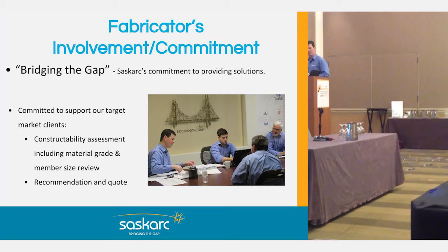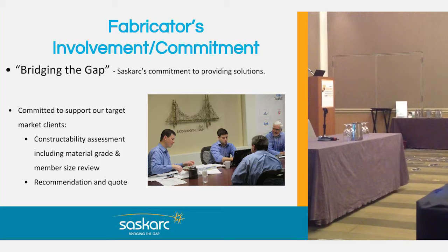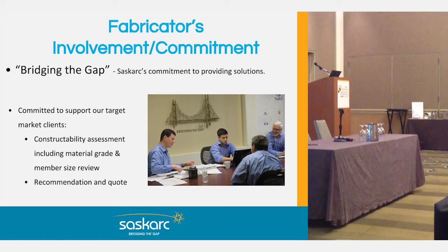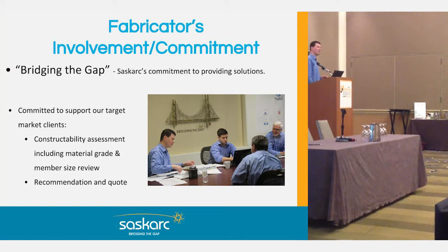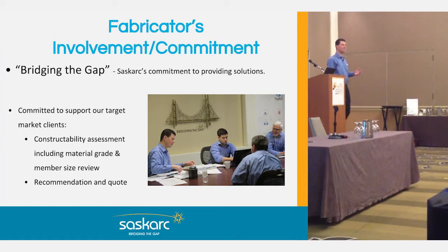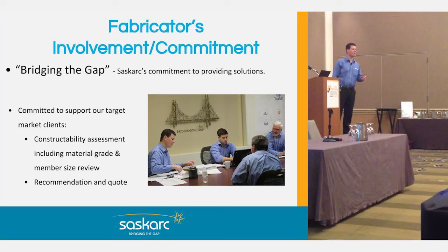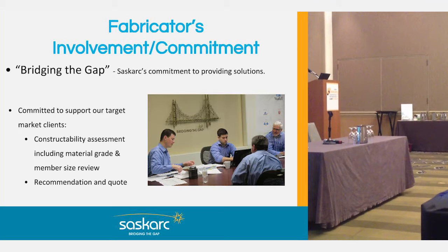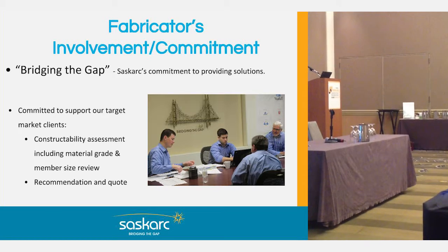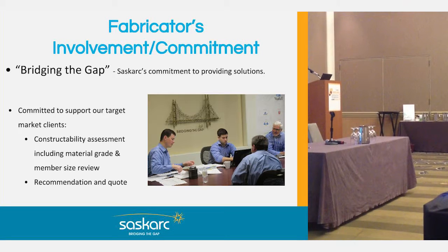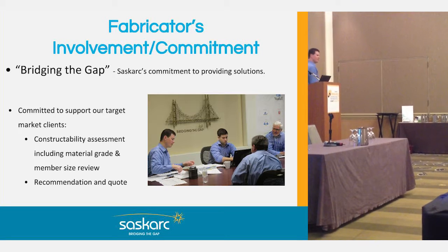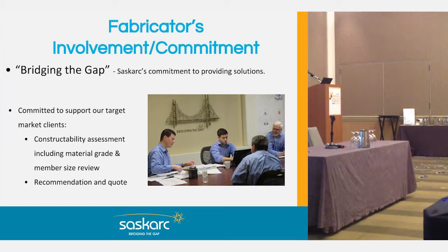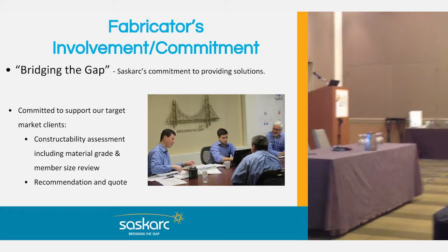So I'm sure many in the audience are wondering, what is the fabricator's involvement and commitment? We can't speak on behalf of the other fabricators today, but we can speak to what we're committed to as a company. We're committed to our clients to bridge the gap between what our clients' realized or sometimes even unrealized challenges are. And we're committed to providing that through doing that early stage of constructability and material grade and weldability and member size review, as well as anything else we may see when reviewing it.